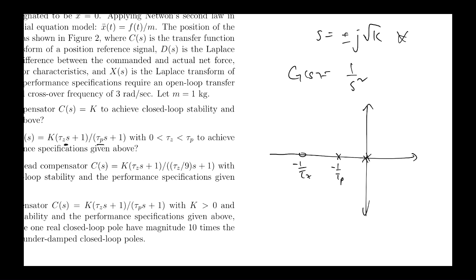Sorry, hang on. How have we got here? We've got three closed loop poles, because there's three open loop poles. So when you write down the characteristic polynomial, it'll be cubic. So there's three zeros of the characteristic polynomial. The zeros of the characteristic polynomial are the closed loop poles. If you write down what the characteristic polynomial is, it's A(s) times L(s), the denominators of the plant and the controller.